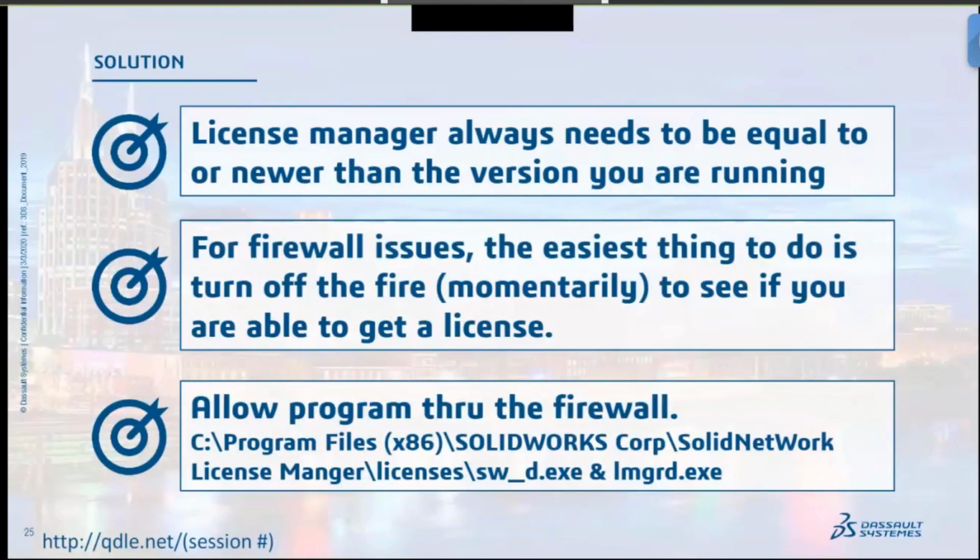All right, so if your client version is newer than the license manager on the server, then we will throw that error. SOLIDWORKS Standard is the core product of SOLIDWORKS. No matter what license you have, the base package is always pulled. So SOLIDWORKS always pulls a SOLIDWORKS Standard license. Professional and Premium are add-ins on top of that.